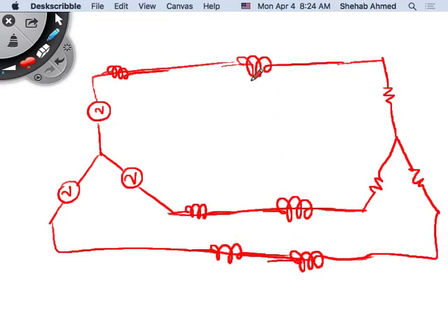Here I'm drawing the inductors of the transmission lines, right? I am ignoring the mutual coupling. I can include it, right? If you want to complicate things further, you can include the mutual coupling, but it will be very small, so we will typically ignore it. For example, we are only working with the short line model of the transmission line. There are other line models that are used for transient analysis, and other line models used for longer transmission lines, right?